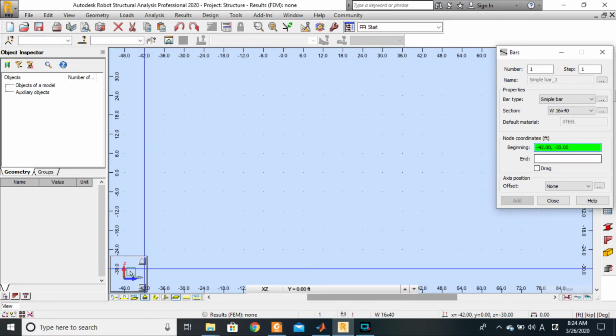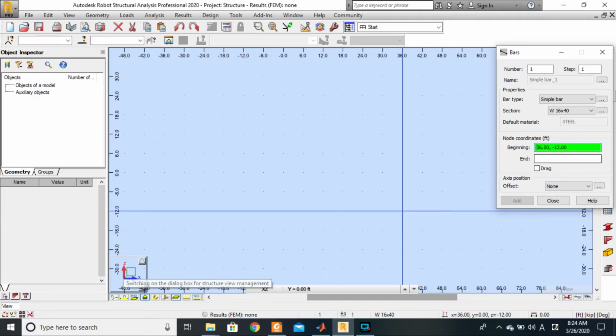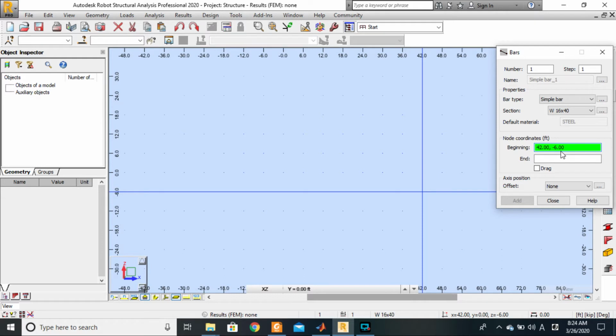Okay, according to what we have as our reference down this way. Okay, so if we want a straight line, if we want a horizontal line, it implies that the coordinates following x have to be the same, no matter where it appears. Okay, so we will start at 0 for y, comma 0. That will be our initial point for the first point of the beam. Enter.